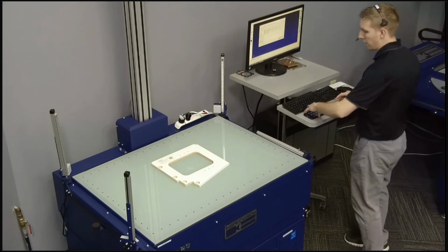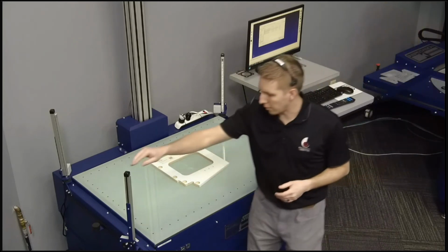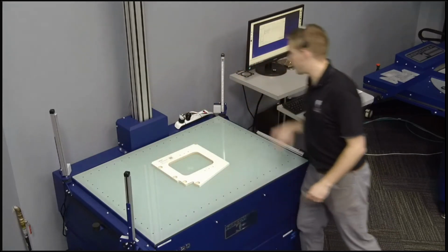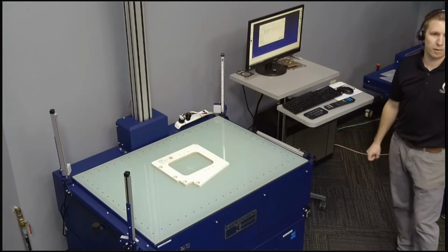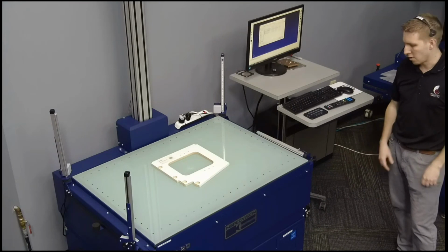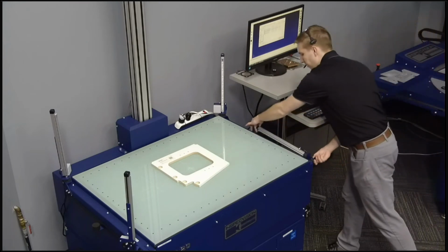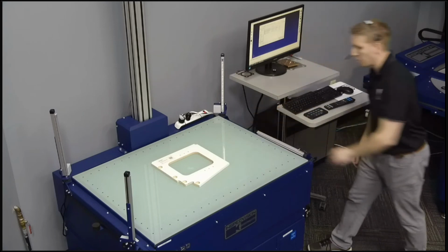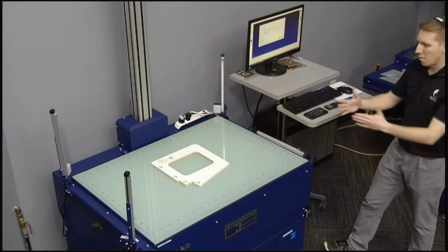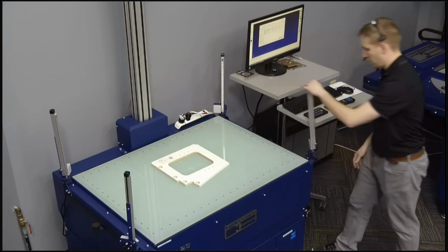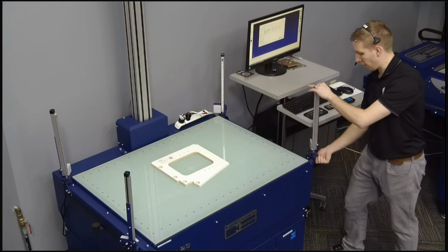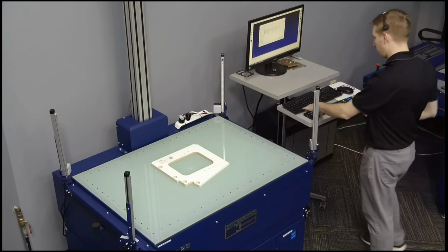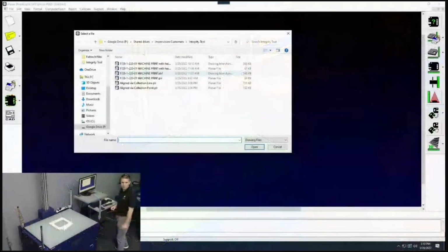So this is our P70 with our demo AOI on it, and you'll see we've got these light pillars that are just on these rubber pads, kind of up in the space, so you can again create those shadows. But what they've also done is put them on these pins so you can get them out of the way. If you have a long part you need to measure, put it down, put a long 2D part in. But when you need it for AOI, bring the part up, lock this in place. Now the light pillar is ready to go so we can create our shadows. So let's go into the software.